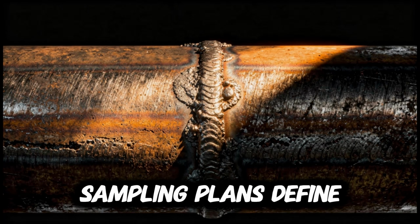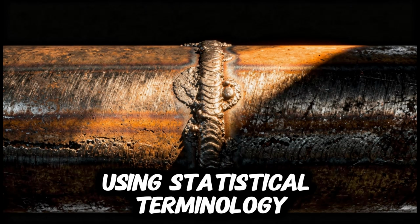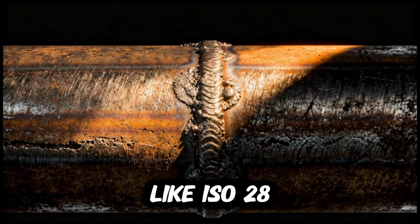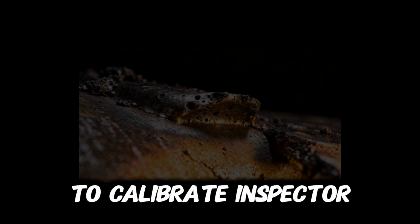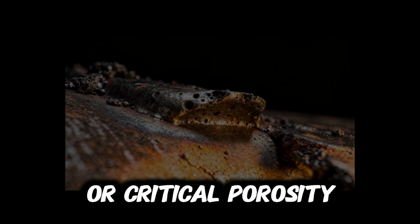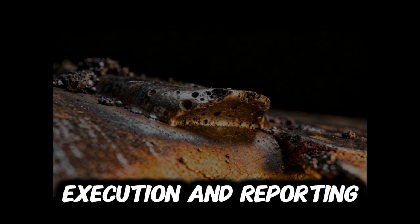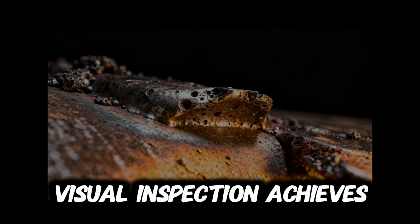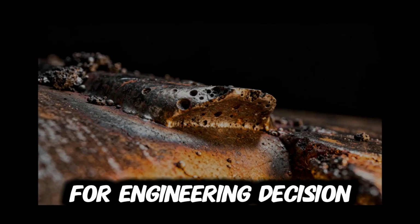Sampling plans define how many components or areas require examination using statistical terminology aligned with standards like ISO 28591. Documented procedures incorporate visual references, photographs, diagrams, or physical samples to calibrate inspector interpretation of terms such as acceptable reinforcement or critical porosity. When definitions are consistently applied across planning, execution, and reporting phases, visual inspection achieves the repeatability and traceability required for engineering decision-making.